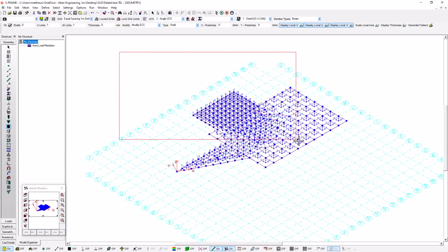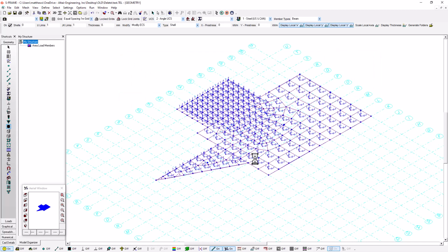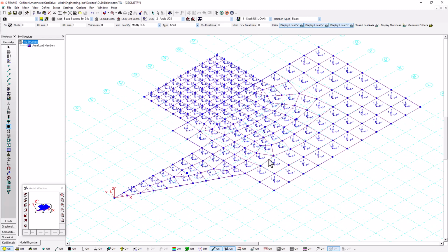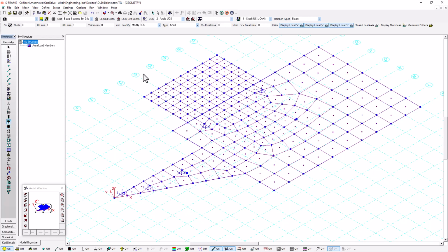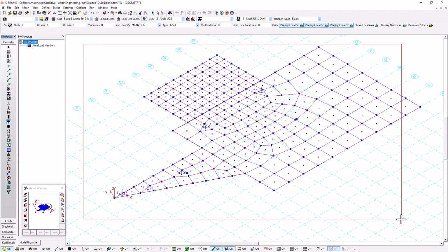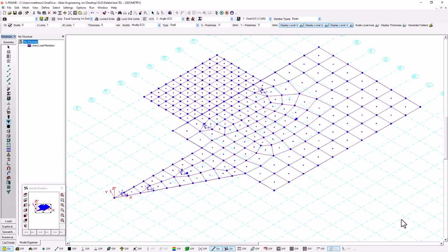Oh, sorry, I clicked too soon there. Left click and drag. And you can see here we got a bit of a preview with my mistaken click there. It's essentially rotated everything to that new coordinate system orientation, with the exception of the triangular elements, which I'll do as well right now. So this can be a pretty handy tool because there are reasons why we might want to view results relative to an element coordinate system rather than a global coordinate system. And this allows us to align that coordinate system in the way that we like.